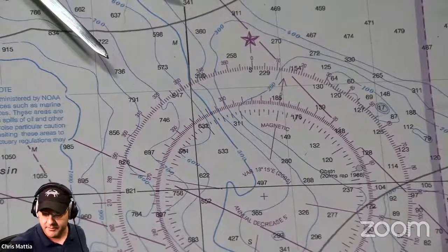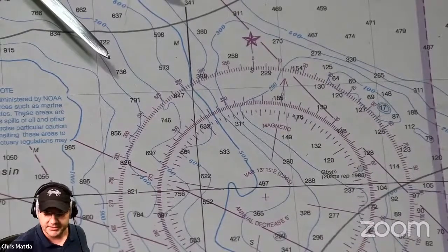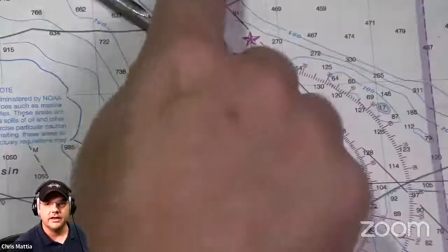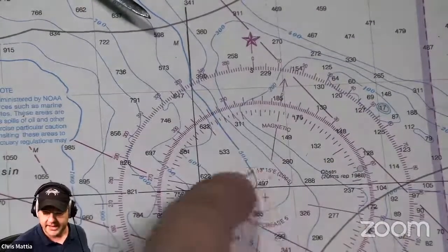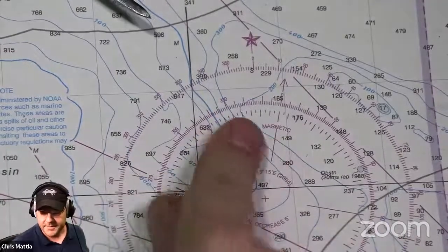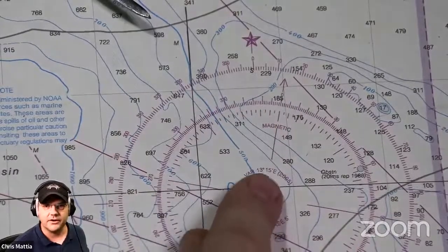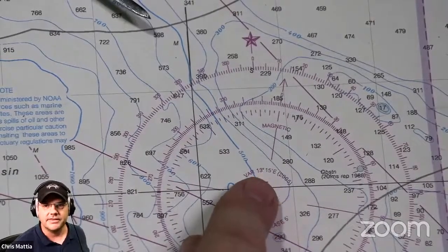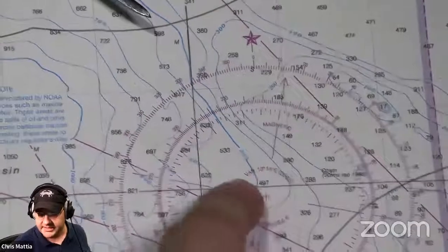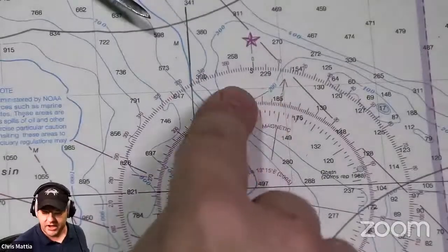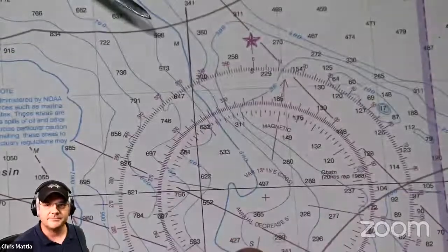So latitude, remember, are the ones that go across like this. These are the lines of latitude. We're going to talk more about those in just a minute. And longitude runs longwise, vertically up and down. So as you go up or down in latitude, the magnetic variation is going to be slightly different. And you'll always see somewhere on the map, usually right around this point, this one says VAR 13.15. That means we're roughly about 13 degrees off with magnetic north from true north at this particular location.